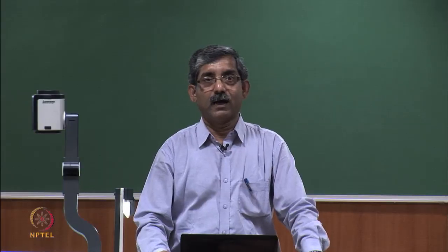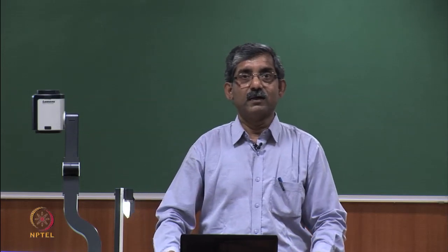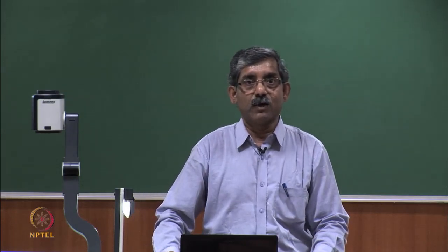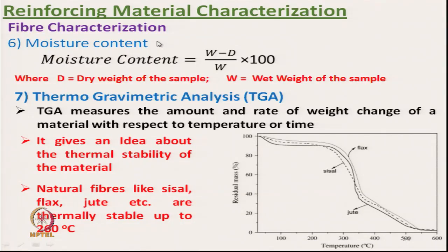And another characteristic of reinforcing material is moisture content. So, moisture content we can measure by measuring the dry weight of the sample and wet weight of the sample.